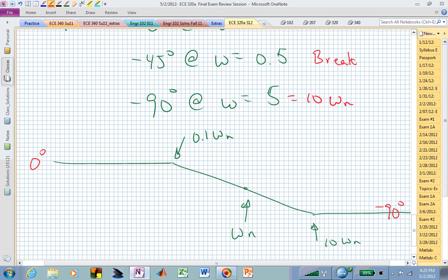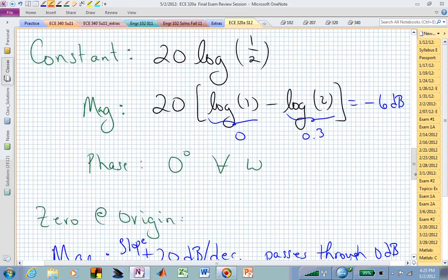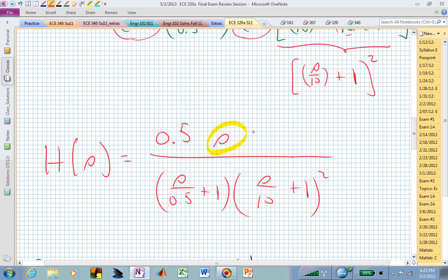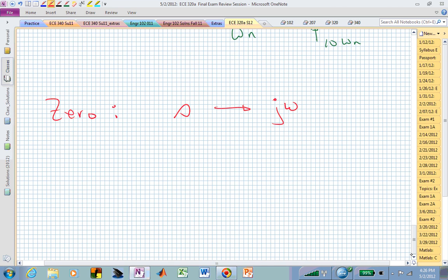Not quite yet, because why zero at the top? The s on the top would stay all the time. So why is this particular piece giving us plus 90 degrees? So if you look at that 0, you have this 0 that's just s, and we're replacing that with j omega. And if you wanted to look at this, you can always fall back on what's happening in the s-plane. Here's your 0 right there, and we are marching up this imaginary axis